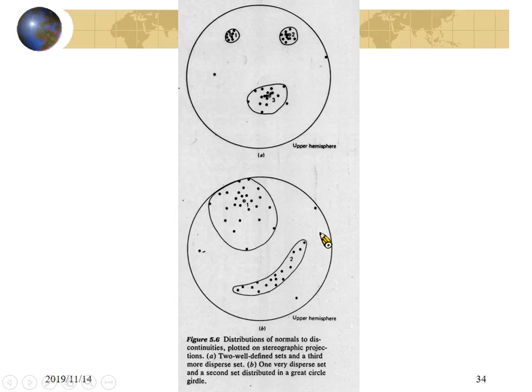It's because of bending. If you have folded rocks, then you usually have discontinuities like this. And these will be the discontinuities parallel to the maximum principal stress. I already showed you, right? And usually you will have 2 like this. We call them conjugate joints. So you will have dip joints, strike joints, and conjugate joints. Please tell me, what is the common feature of those discontinuities?